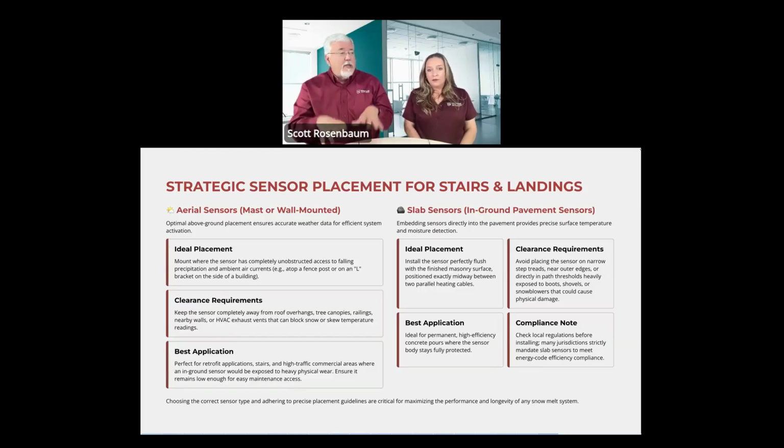That's where you want the sensor, because the sensor needs to be hit by snow every time it snows. And you have to be able to get at it. So don't put it on a 30-foot stalk on the top of your roof that no one can ever get at, because birds love to sit on that little sensor on the top. And what they do is they leave behind a little gift every time that they've sat there.